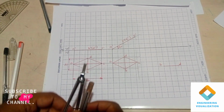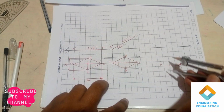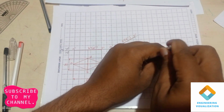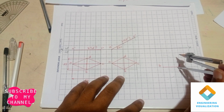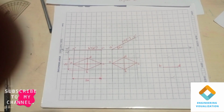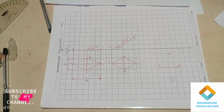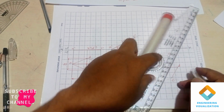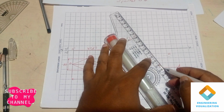Then take the compass and cut arcs: measure from B to A. Any one length is enough, because B to A and B to C are the same. You can cut above and below by measuring the same length, and then cut the same from point D. No need to measure again. Now join it. This point is A and this point is C. Now in this position it is parallel to the VP plane. With respect to the question, it is parallel to both the principal planes.